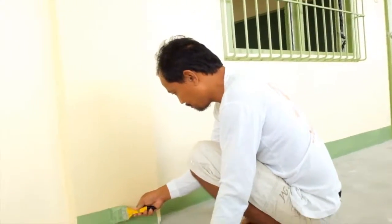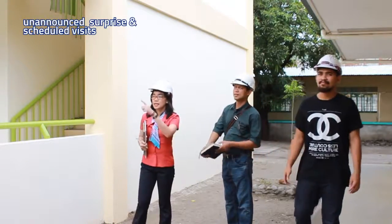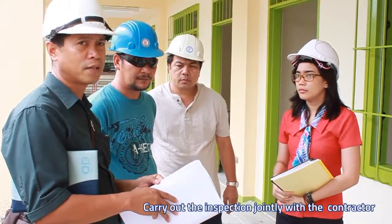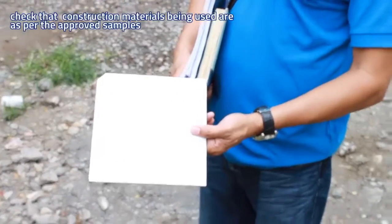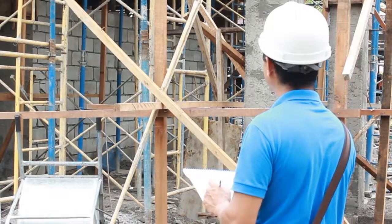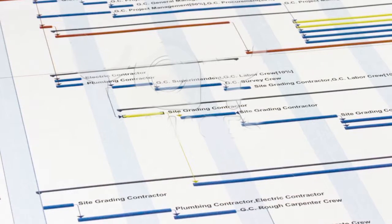For both unannounced and surprise visits, and for each of the 6 scheduled key inspections, the engineer should carry out the inspection jointly with the contractor. Where possible, the school principals should also attend. Check that construction materials being used are as per the approved samples. Check that construction is progressing as per the drawings and specifications. Check the progress of the work against the construction schedule.